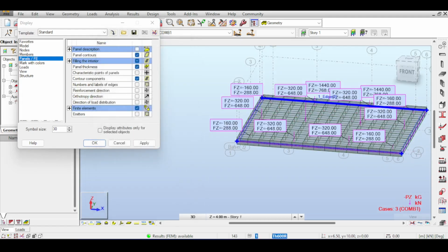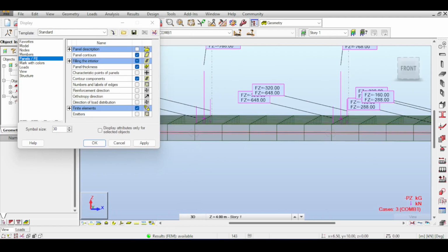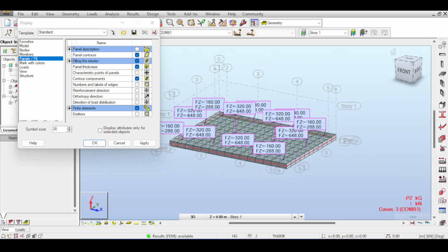Now I see the thickness. What I'm trying to say is the load that is applied on the raft gets distributed using the 2-to-1 method, or whatever method you see fit, meaning that this load actually arrives at the soil not as a point load but as a distributed load on an area. So that's the second thing that I want to talk about when comparing what you get in the finite element method versus what you get in real life.